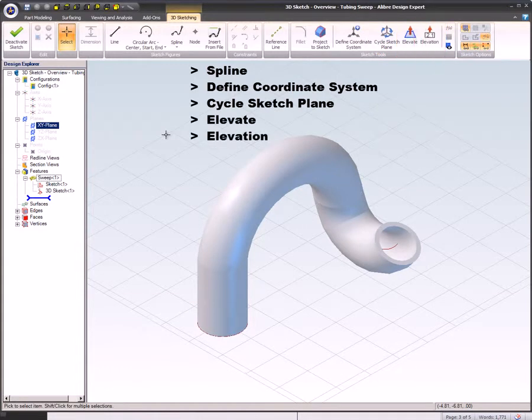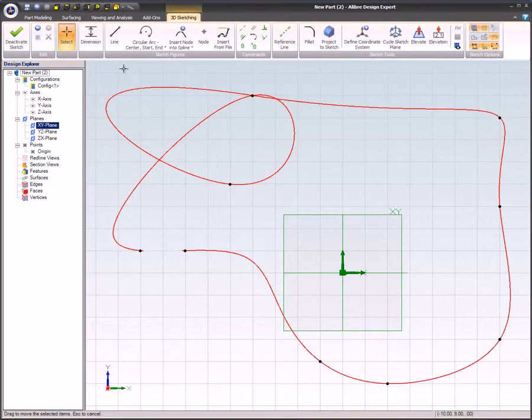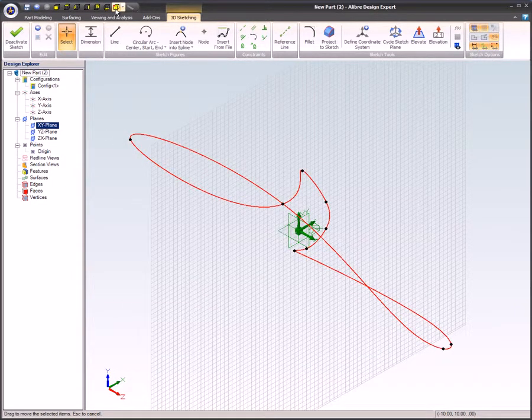Generally speaking, 3D sketching should be used with a grid active so it will give you a reference as to where you are sketching. It's important to understand that with 3D sketching, you do not need to sketch on a planar face or plane. However, if you're not sketching on a plane, your sketch could end up out in space.